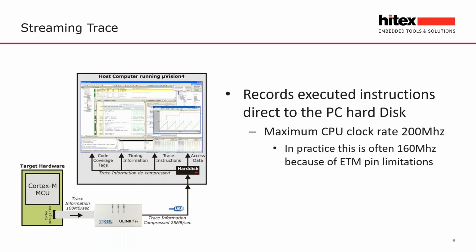So if you are designing a project and intend to validate code with the trace, you need to be aware, do some preliminary testing, or be very careful with your board layout to get the maximum trace speed.